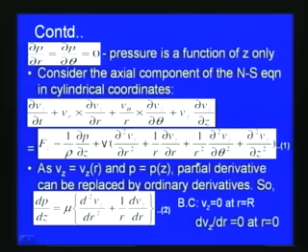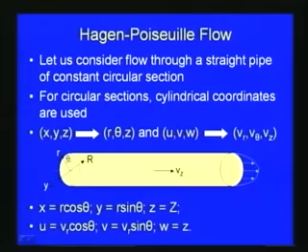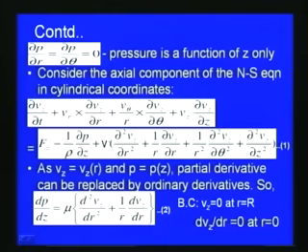Here, as in the previous figure, we consider a horizontal pipe, so we do not have to consider the body force for this particular problem. We consider the flow to be steady state, so the del V z by del t term, the time dependent term, vanishes or is 0. And then, the velocity V z in the z direction is varying with respect to the radial direction.